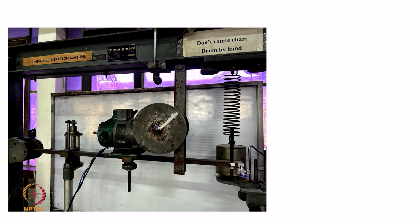Okay. Now, to further understand this phase, which is not so much talked about, interestingly I will show you how this phase is actually physically manifested through a setup that we have in the lab. So, this is a simple vibratory system in the form of a beam which is hinged here. There is a fulcrum, and this beam is supported by a helical coil spring at its tip somewhere here. So, there is a restoring force due to this spring that is going to pull this bar up when the bar tries to go down.